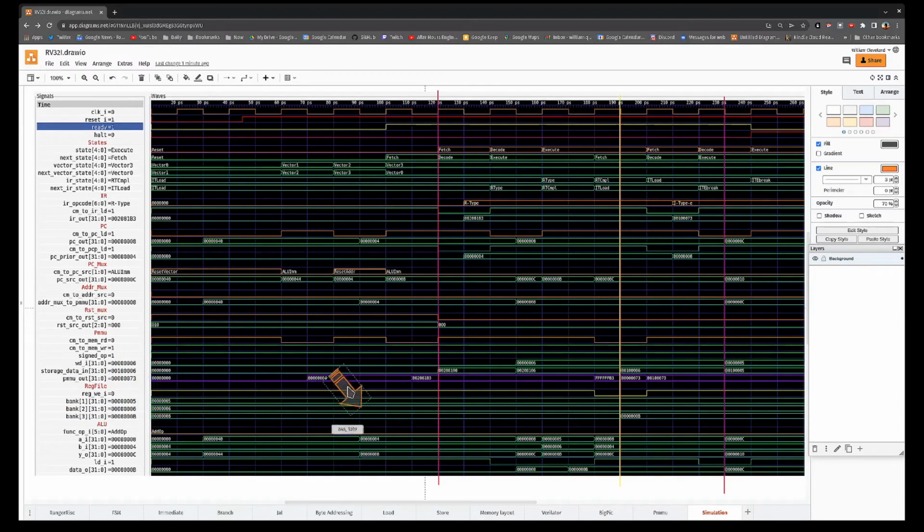Next up would be the fetch sequence for the instruction itself, and that's where it is determined that it's an RType, and there is our instruction. So far things are looking good. Another thing to look at is the program counter. We started at our reset vector, we found our first instruction, then we auto-incremented to the next instruction, and then auto-incremented just before the break. So that's all going according to plan.